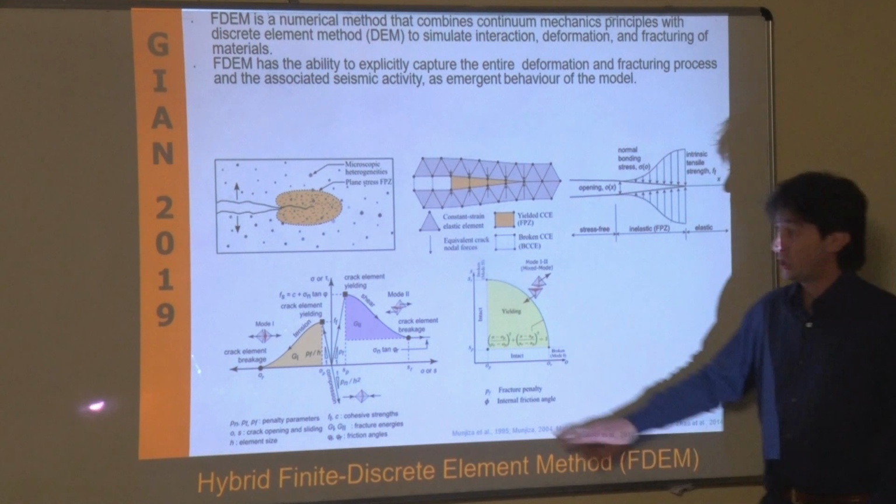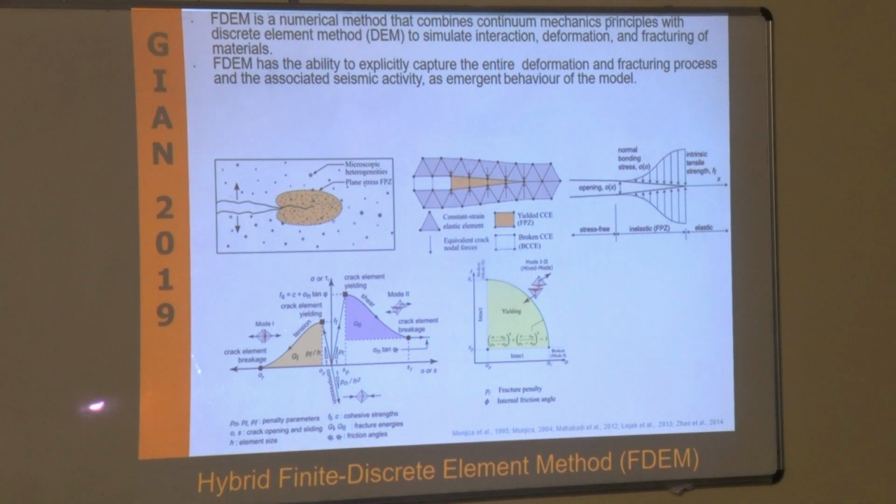The shape of these curves is actually empirical and derived from experiments where the scientists were actually able to measure the stress and the displacement of a mode 1 fracture. How do you do that? You create such a rigid system that you actually can follow the loss in cohesion of your sample while you are applying a pure tension. Extremely difficult measurements. They did those measurements, and that is the empirical equation that has been developed following those tests.